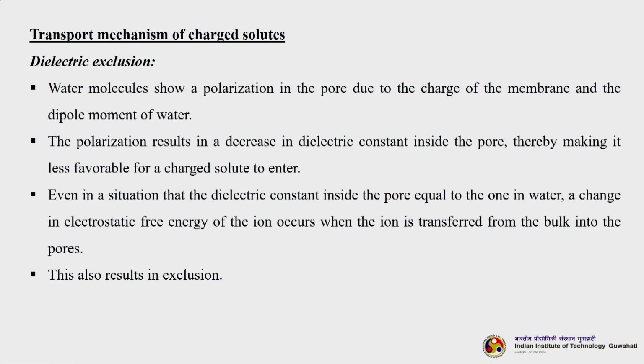The next one is dielectric exclusion. Water molecules show a polarization in the pore due to the charge of the membrane and the dipole moment of the water. The polarization results in a decrease in dielectric constant inside the pore, thereby making it less favorable for a charged solute to enter. That means, when the water is getting polarized inside the pores, it is hindering the diffusion of solutes inside the pore. This is what is known as dielectric exclusion.